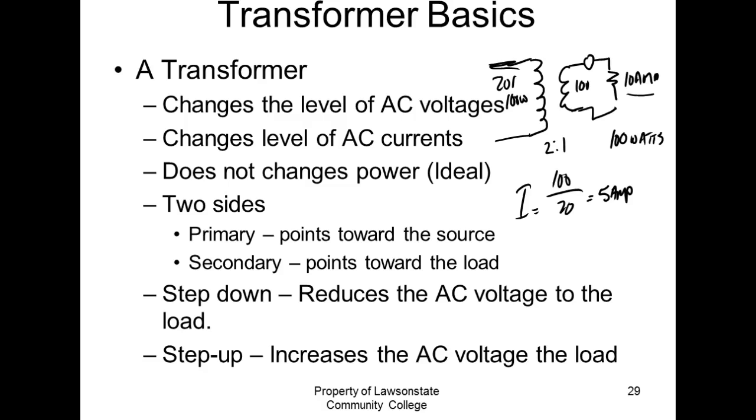transformer. By the way, big commercial transformers, don't call them primary and secondary. Most commercial transformers can be wired either step up or step down. So commercial transformers usually refer to the transformer as the high side and the low side. So the leads on the high side are going to be labeled with an H. It might be like H1, H2. And the low side, we're not going to use L because L we use for inductors. So the low side is going to be X, like X1 and X2. So that's the way the transformers, these are commercial transformers.